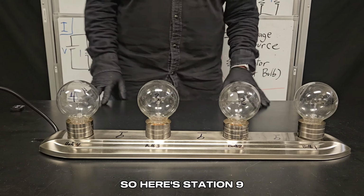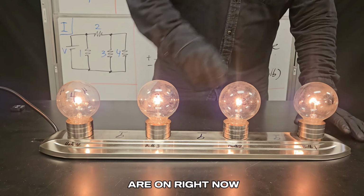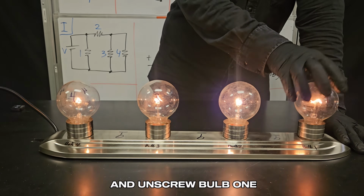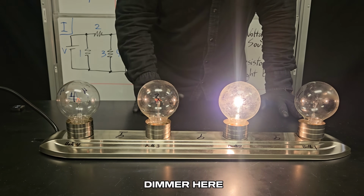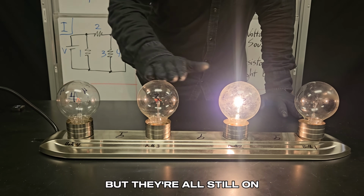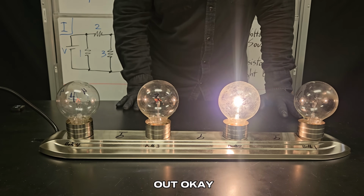Okay, so here's station 9. Let's go ahead and turn it on. And so all the bulbs are on right now. I'm going to go ahead and unscrew bulb 1. And it does look like bulb 2 got brighter and 3 and 4 got a little bit dimmer here, but they're all still on. So unscrewing bulb 1 did not cause any of them to go out.